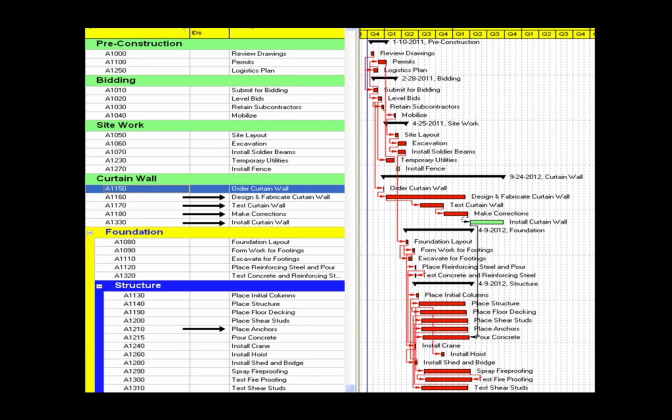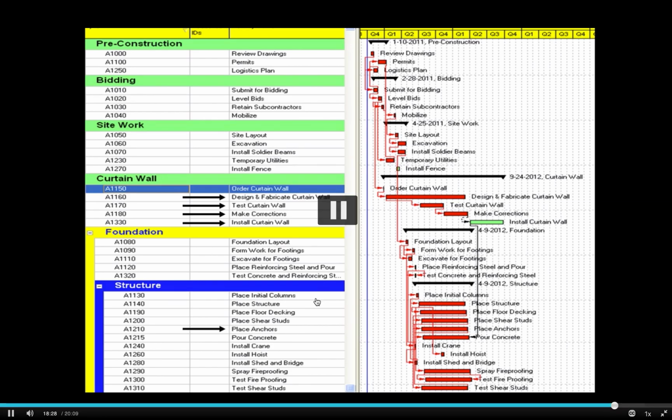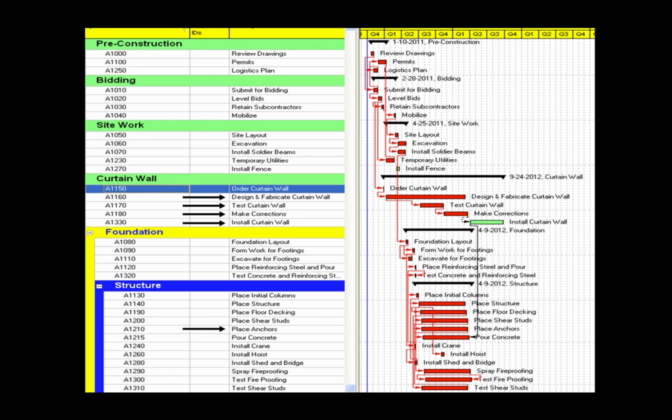So make sure that all your drawings match up, that you have a working drawing that calls out all the elements. It's not just the framing of the concrete or the rebar, you actually have everything in place. And it's very important to have coordinated drawings. Those working drawings are just as important as the contract plans or shop drawings.